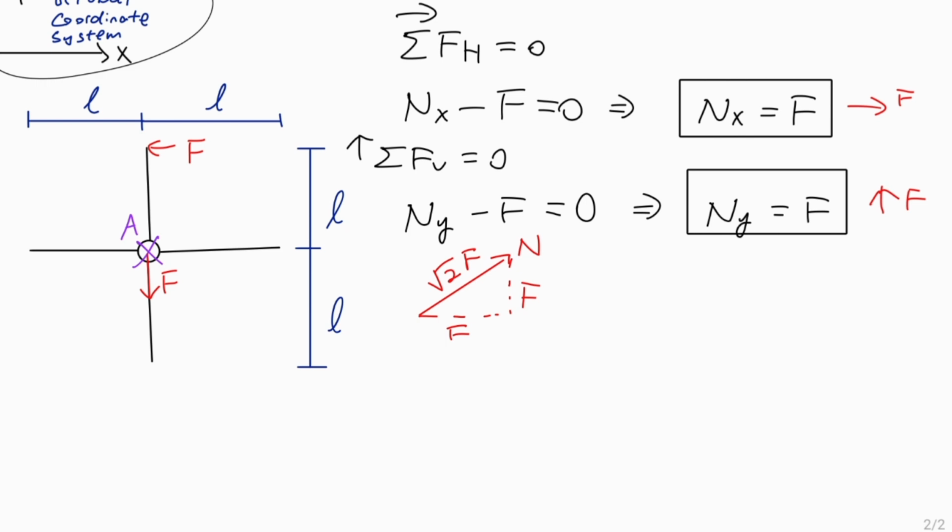So my moment balance now has to cause this to be in moment equilibrium. Now if we just look at this picture, this doesn't induce a moment, but this one does. This one induces a rotation in the counterclockwise direction, right? So I know that my point force has to be put somewhere such that it induces a clockwise rotation that cancels this out. Now, thing is, you can actually put this in infinite different locations, okay? It can be here, or maybe here, as long as the moment, actually this one's impossible, but as long as this can generate a moment that's big enough to cancel this force, you can place it technically anywhere, okay? So there's, in reality, infinite solutions.